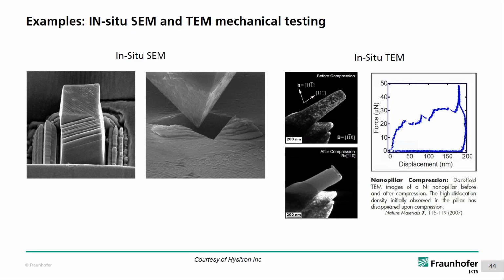You can also do it at different scales, at different sizes of the particles, and normally you get a size effect if you have really small nanoparticles where there are very few dislocations inside, or big particles that behave differently, so you can check the size dependency of the behavior. This is something you can do ex situ, but it's easier in situ because you have better positioning and you see what happens to the particle when you compress it.